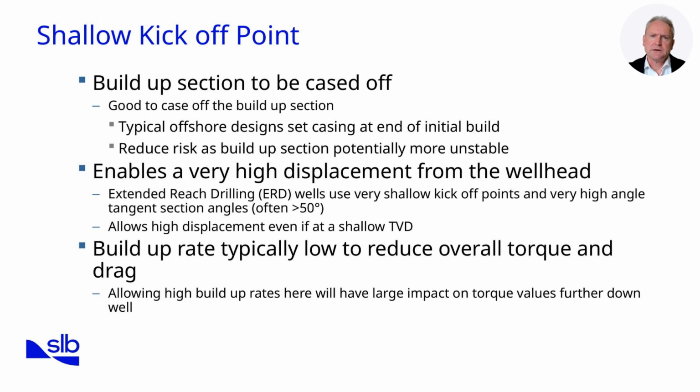Shallow kick-off points are often favoured for offshore and ERD wells. They enable the build-up section to be cased early, reducing risk in potentially unstable formations. This design allows for long horizontal displacements and tangent angles greater than 50 degrees, which is ideal for maximising reservoir contact at shallow depths.